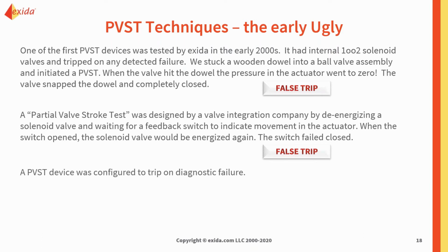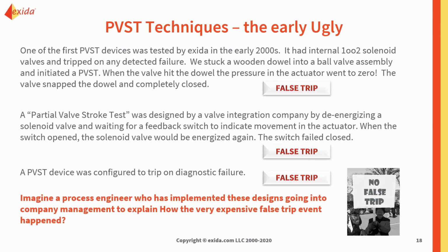We've also seen a lot of engineers design PVST that's configured to trip on diagnostic failure. But our analysis has shown that this again results in false trips. So imagine being the process engineer that has to explain to management what happened on this expensive false trip event. I mean, really, if that was me, I might never use PVST again, honestly. I've met a lot of people that feel that way. And if that's you, I encourage you to listen further, and we're going to continue to investigate this together.